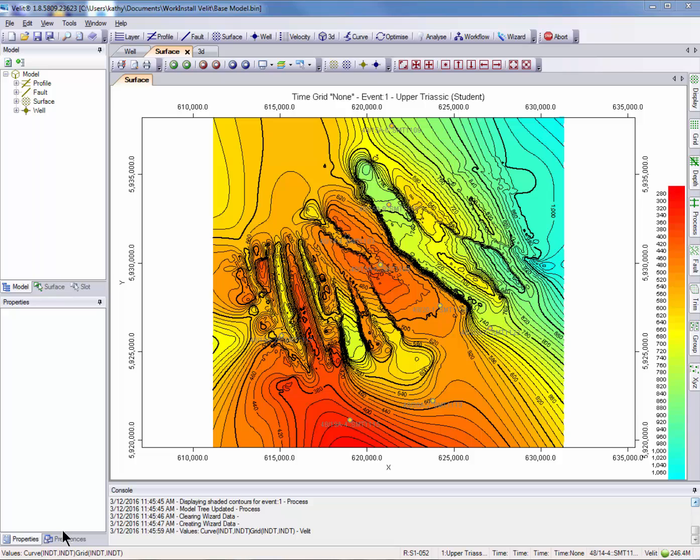If you have long well names with UWI formats, you can tidy up the well annotation by clicking on the Preferences tab in the bottom left of the main window and toggle Name and UWI to No. Double-clicking on Name, Number and UWI is usually faster than using the drop-down.